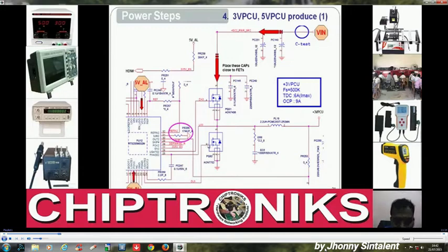You see LGATE2 is fed to the gate of the lower side MOSFET. So it supplies power to the gate drive circuit which generates the gate signal, right? The LGATE2 gate signal. And please, I'm going very smoothly over here, but I'll go into details when we look at the datasheet of this circuit, okay? I'm just going through the steps. What steps are there? How is 3.35 volt generated? We are going through the exact steps, okay?